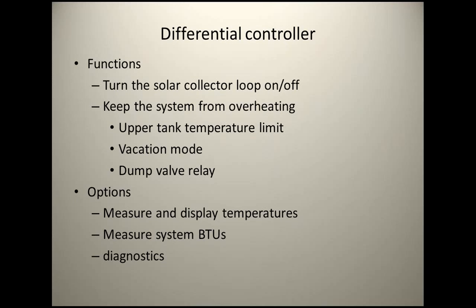So what triggers that bypass? Same thing. If you get to the point where your tank has all the capacity, then mine was done by pressure. Because as the temperature heats, the pressure rises. So if it got to a certain pressure, it would kick on and actually bypass. It would leave what was in the tank, and by pressure would go out and run through the loops, and I would pull it back at 60 degrees.